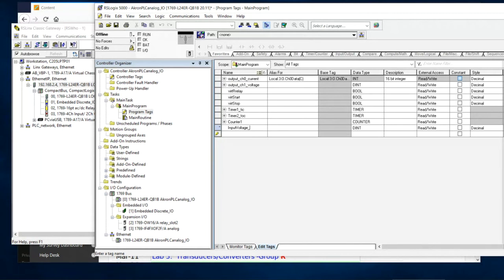and when we go to the configuration, I haven't actually configured my analog card yet. When we go to configure that, we can configure it in different ways. Okay, so we're going to have an input voltage and an input current. Okay, so it's going to be channel 0. Channel 0 is going to be an input. And input channel 0.